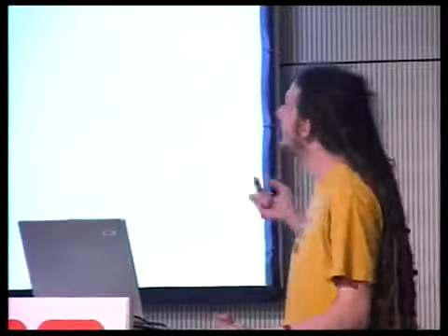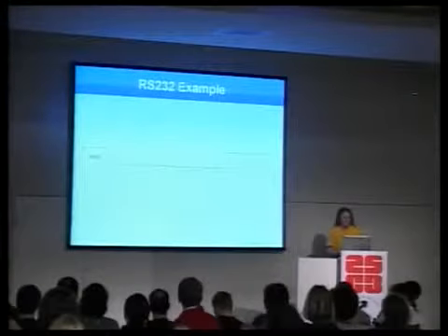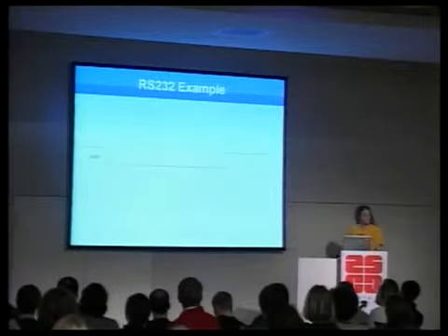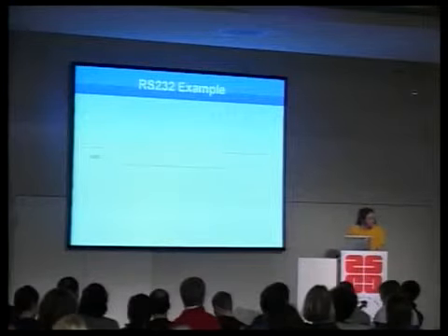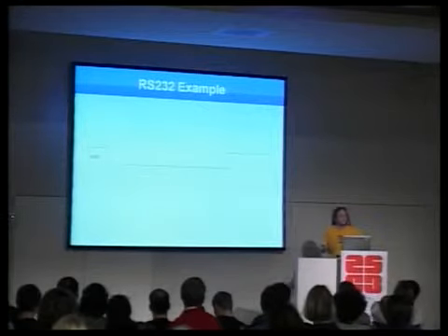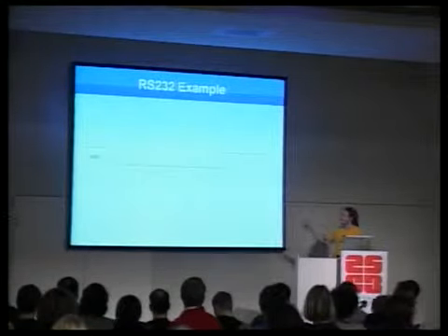Now, 0x80 is sent before any given command frame to the bootstrap loader. Do any of you know why? For what? Make it wake up? Not quite. This is how it determines how quickly the transmission will be.